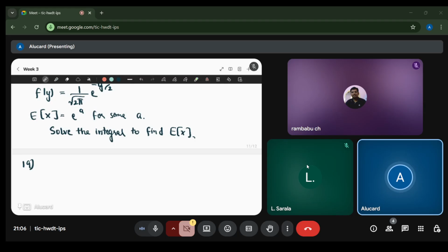Consider log normal shadowing effect with sigma equal to 6 dB. Given there is a maximum power constraint of 1 milliwatt that a base station can transmit, find the maximum radius of the cell for 95% coverage probability. Assume the free space path loss model, and you are given that Q of 1.644 is 0.05.